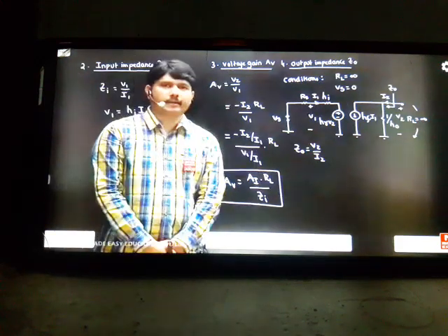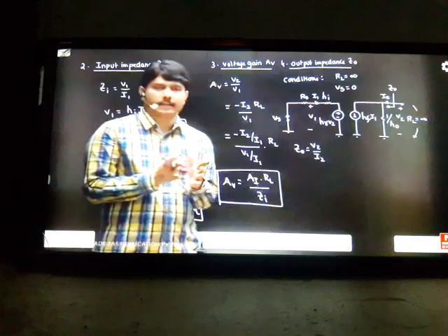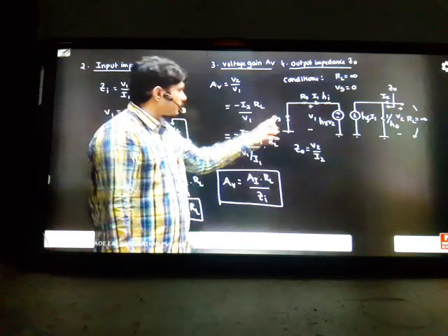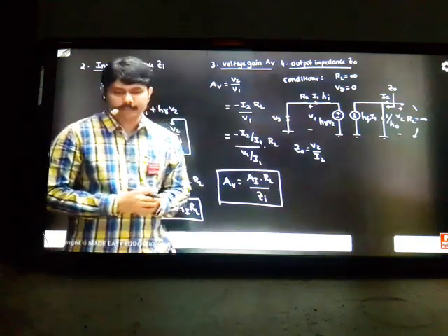How many times should I tell you? Again you are asking what the conditions are? What are you saying? To calculate output impedance there are two rules. Make RL infinite and short the input source. Write the diagram there too. So what is the meaning of asking again? Please explain the conditions.